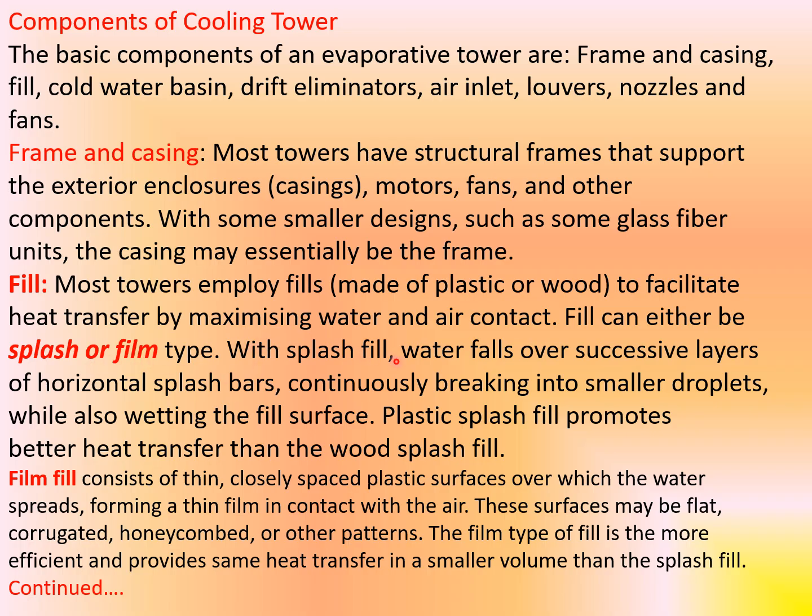With splash fill, water falls over successive layers of horizontal splash bars, continuously breaking into smaller droplets while also wetting the fill surface. Plastic splash fill promotes better heat transfer than the wood splash fill.